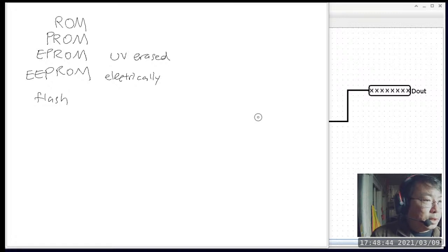No, not mechanically, but electrically, ROMs and RAMs are entirely different. RAM can change a whole lot faster compared to any flash memory. RAM is changed while it's running. EEPROM is changed by a different device. That is true, and flash is interesting too. When flash memory is being changed, it cannot be used to supply content. That's kind of a tricky thing because you cannot run a program from flash memory and update the flash memory at the same time. Not usually, unless the device is designed to do that. Flash memory cannot do that.